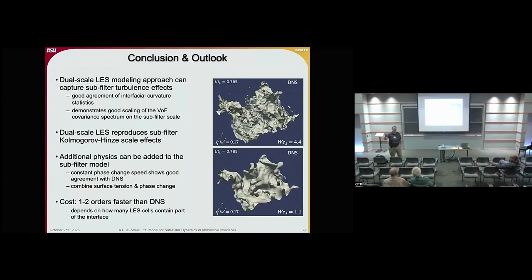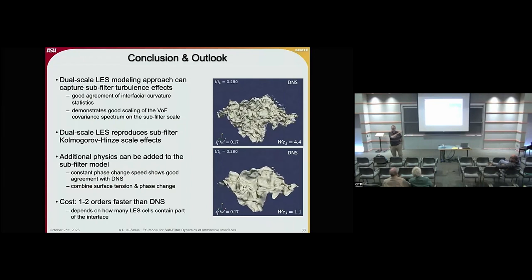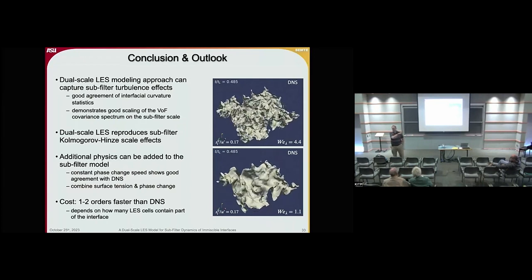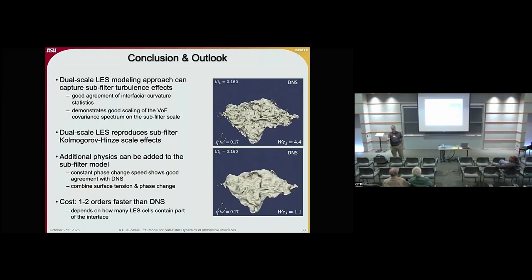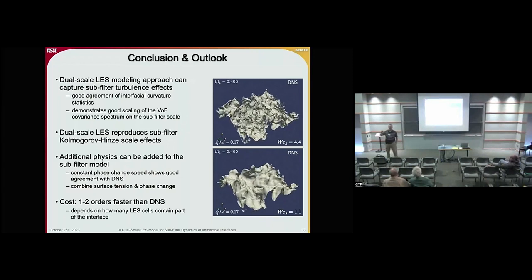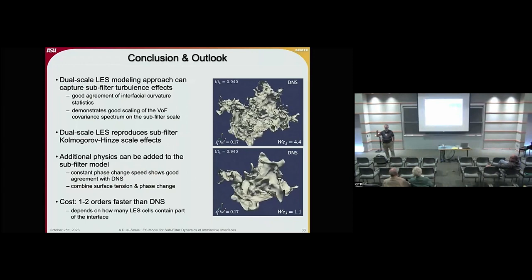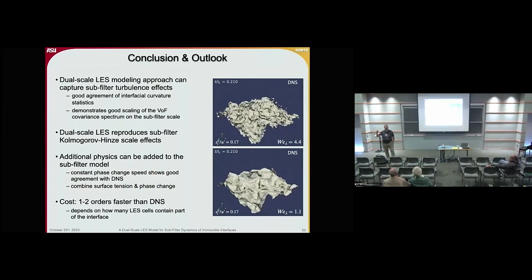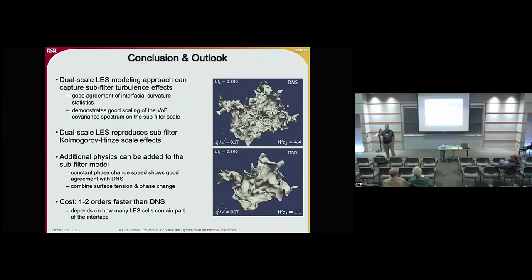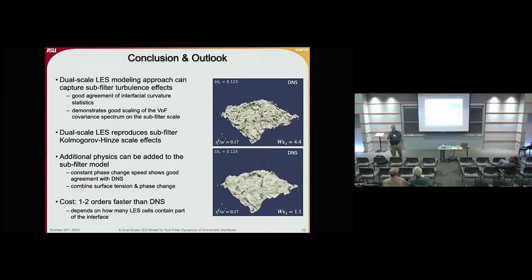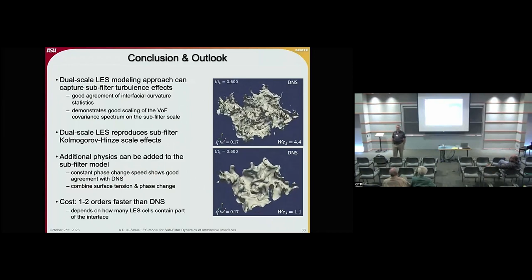If you now go to the DNS scale, you could enhance that with fluctuations like we do with the velocity, perhaps to get variations locally, spatially in there. And then you have to account for, what is it, tangential surface tension, the term escapes me, variations in the surface tension inducing flow fields. But that might not be that important in these high shear atomizers.